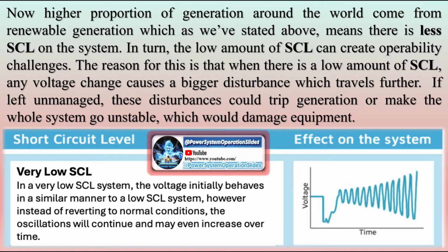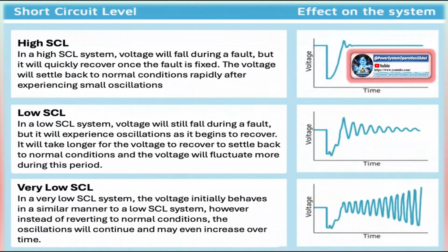Regularly assess SCR, especially when integrating new generation sources or making significant changes to the grid. Utilize software tools for complex systems to account for dynamic changes in the network. This calculation is crucial for ensuring system stability and reliability, especially in the context of increasing renewable energy integration.